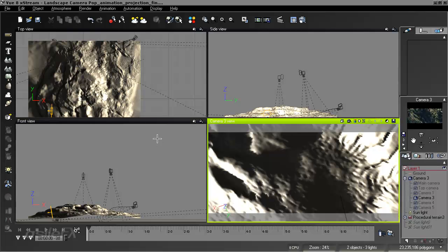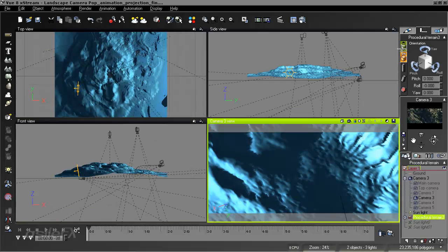So if you're going to be doing this, you might want to lock the camera first before you render. If you end up changing it, then you can update that. But that way it keeps it in place, because the decimal point values are only going to go so far. So there might be a slight offset the way I just did this, because I rendered first and now locked the camera. Depending on how far the decimal points go within the output, because I'm just copying from the numerics tab, which only shows so far, the rest of the values are being cut off. So even if it is different, it's not going to be available. So one thing to keep in mind.